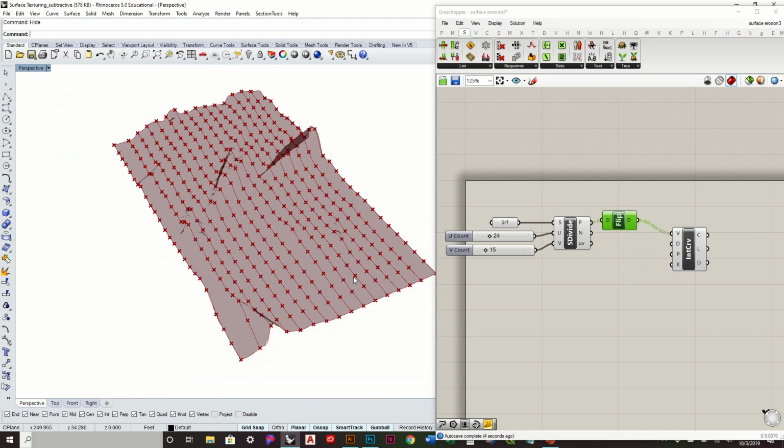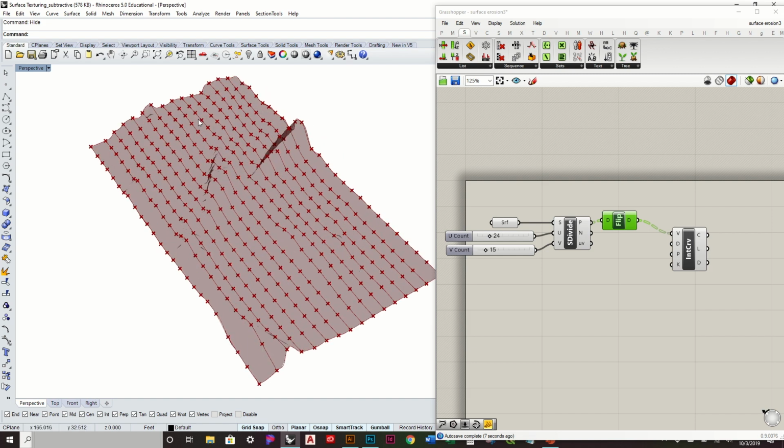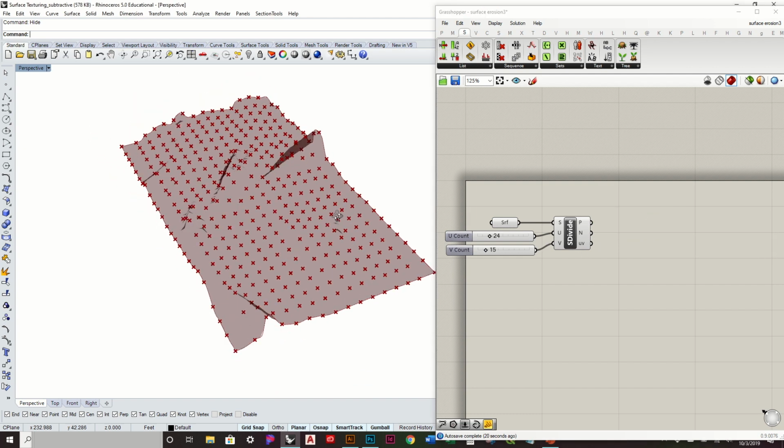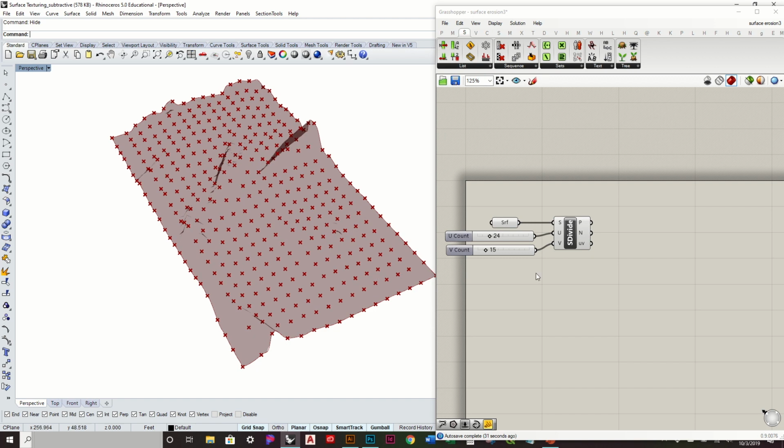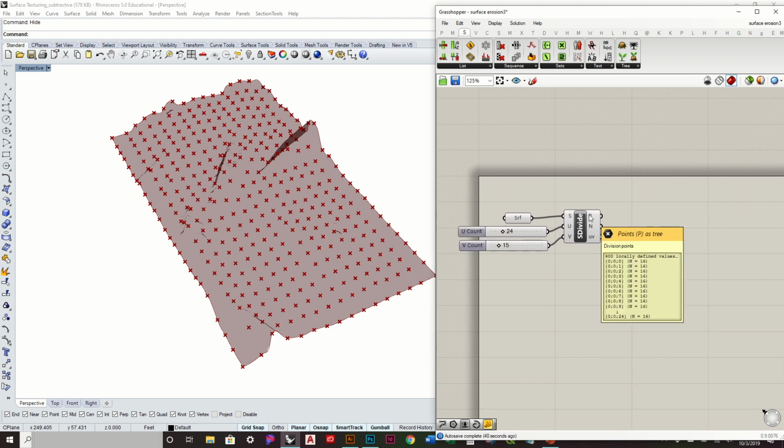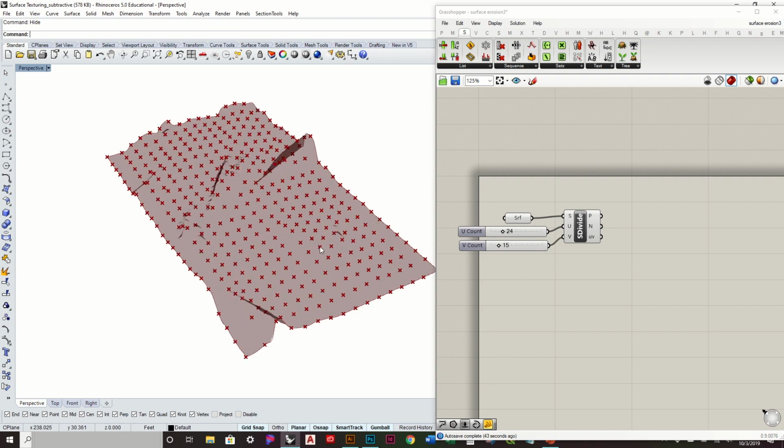And for something that's long like this, I actually want to stick with this direction. I'm not going to actually apply the curve yet. I'm going to do something a little bit differently. So we can stick with this. So like I said, we can use two different parameters. I'm going to use them separately, where you can use an elevation one as well as a slope one. I know you guys are hopefully familiar with the slope condition by now from a lot of those other previous videos. So let's just try something different with the elevation in this case.